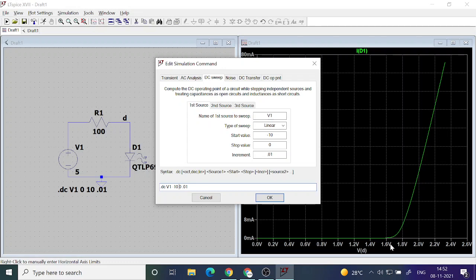across the diode, making it forward bias and making the current flow, and this current is what generates the light. No current, no light. So if you want to see an appreciable amount of light coming out, at least some 1 milliampere current should flow. Otherwise you may not notice. If microampere current is flowing, you may not notice any light coming out of these LEDs.